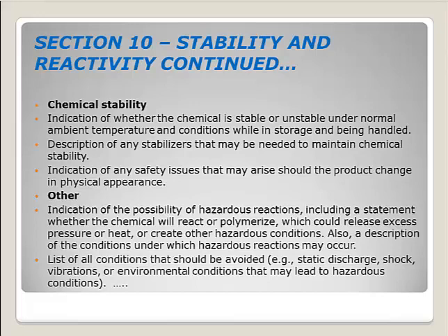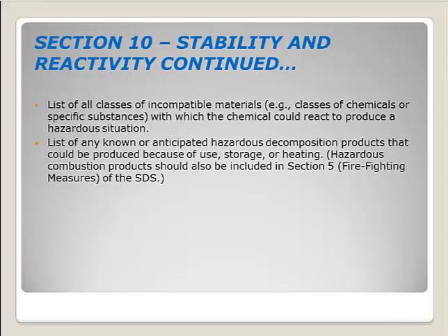And any other item that needs to be talked about with the particular item would be discussed under the other section, something as static discharge. So storing this item in a metal container, you may have to bond the metal container or ground it to make sure that there's not a static buildup as a result of storing this item. Okay, list of all chemicals or classes of incompatible material. So that would also be included in there along with other items as well. Anything pertaining to storage and use of.